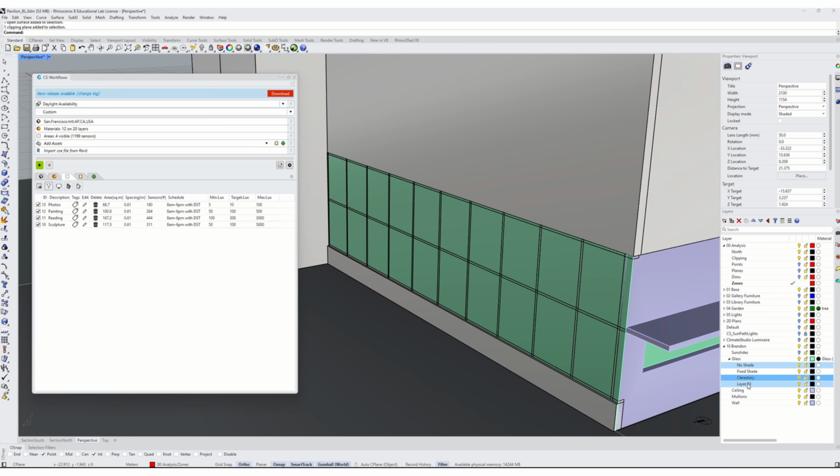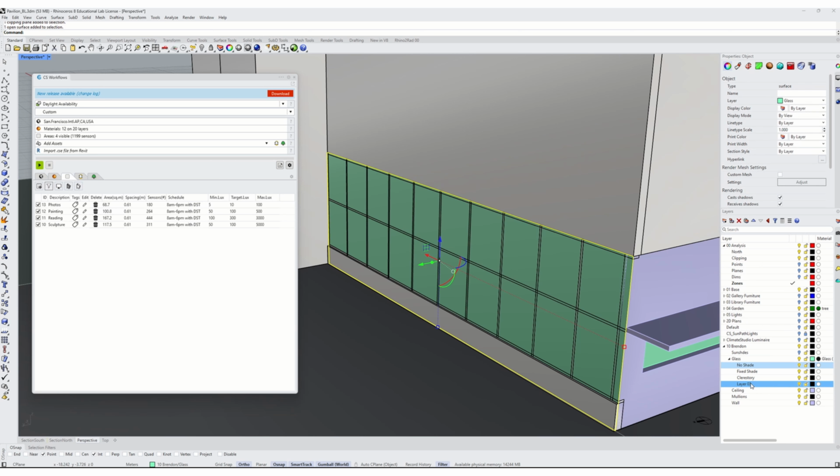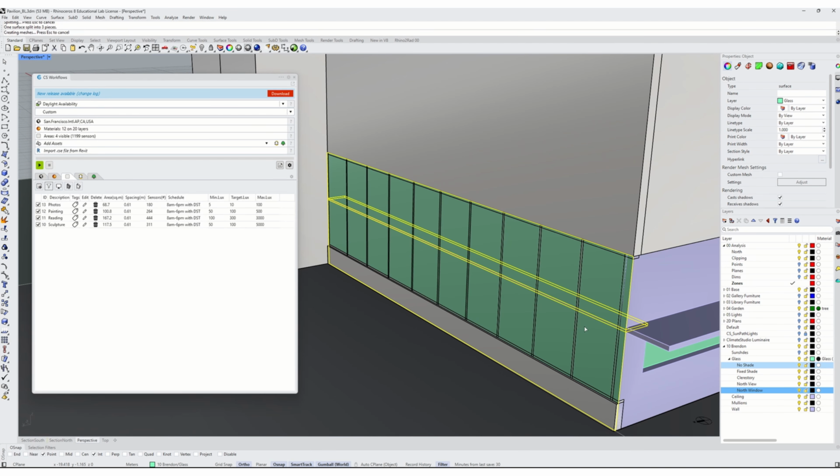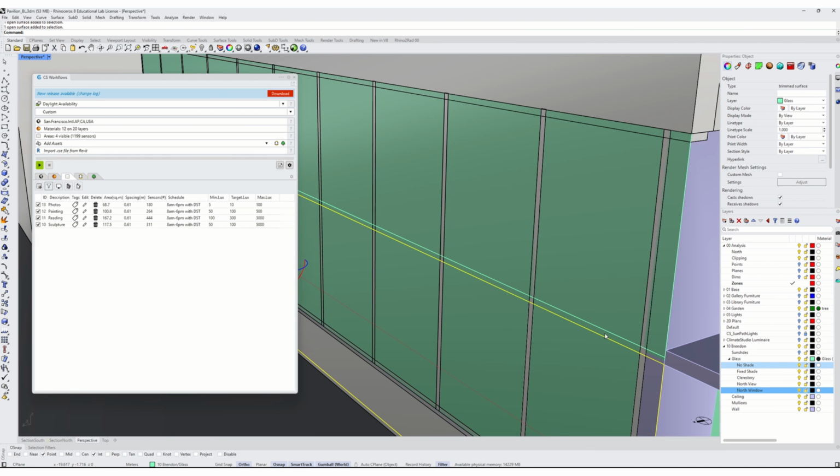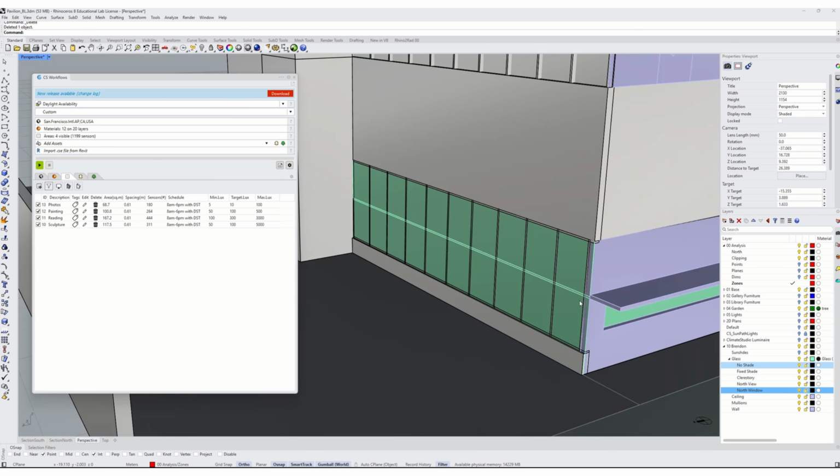This glass is here, and I'm going to name it north view glass as opposed to north clerestory glass, or I'm just going to call this north window. And I am going to split this with this mullion. Let's see if this works. So now we have an upper and a lower, and actually I think we have one in the middle too. I'm going to delete that.